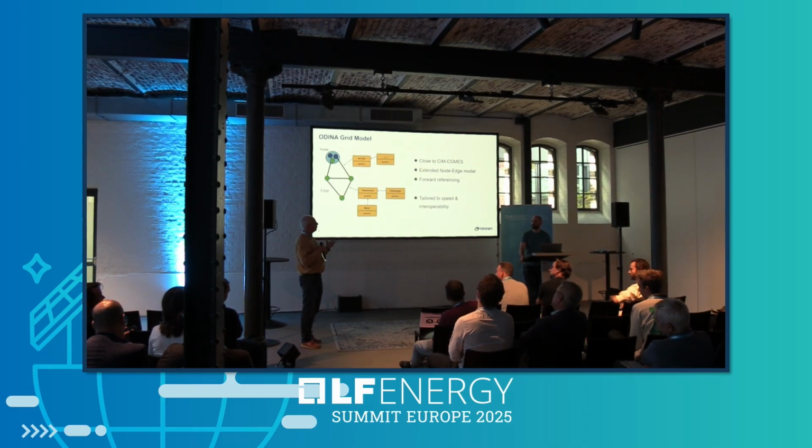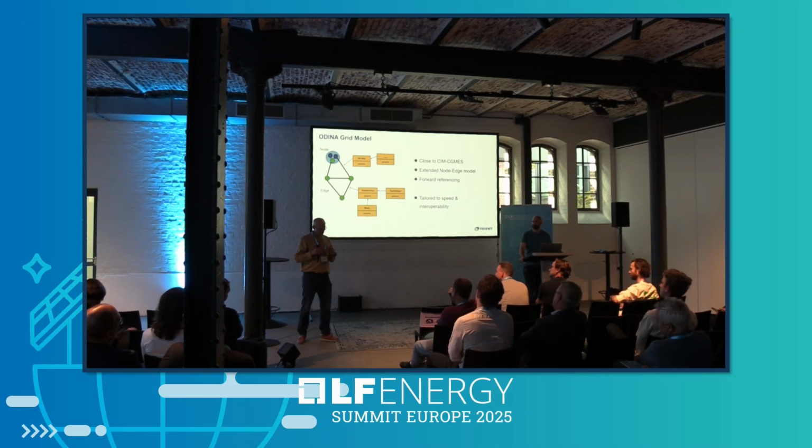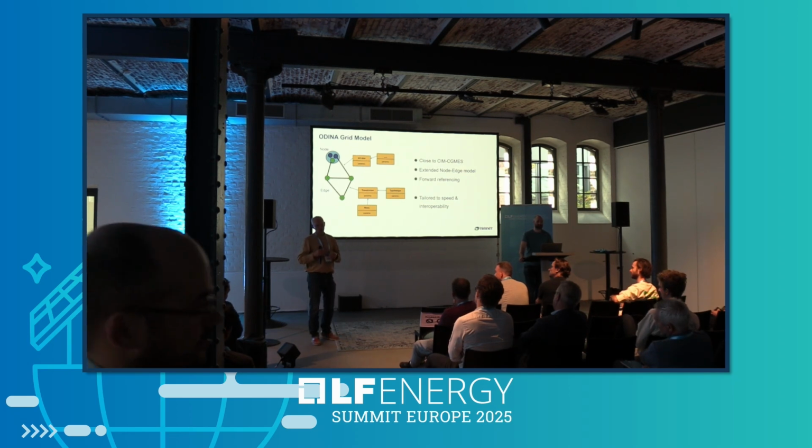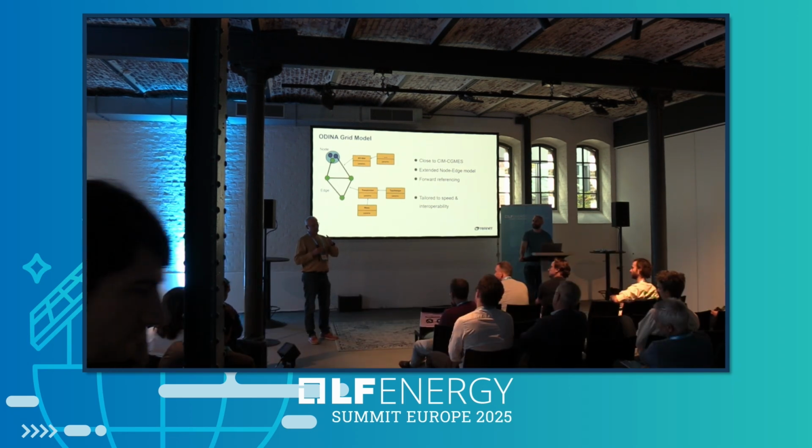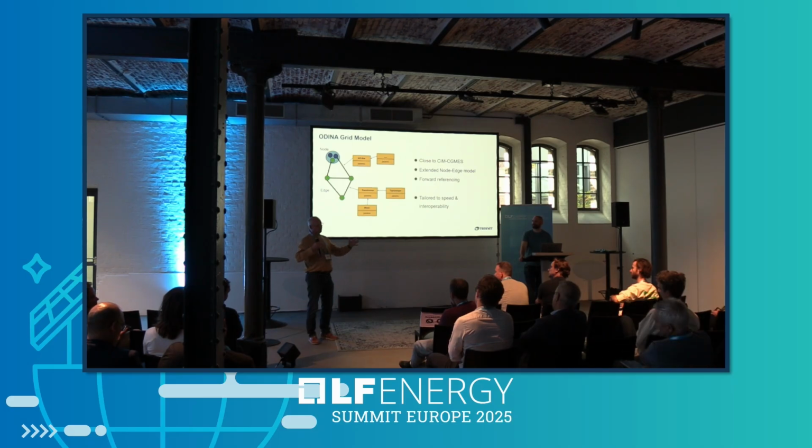Because in the linear load flow, you can calculate load flows for multiple hours, N-1, in one single matrix multiplication. So we have a big matrix, two of them, you multiply them, and what you get is the load flow for all the hours in one single action. That's what we do. So we do a year-round load flow in 20 seconds on a laptop.